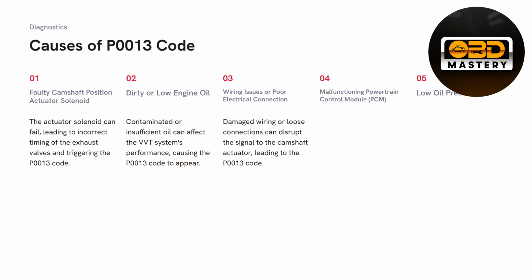Wiring or poor electrical connections. So check all those connections. A lot of people think it doesn't really matter, but it really does. If you're not having a specified voltage or a consistent voltage, that will really throw off every other sensor in your car as well.